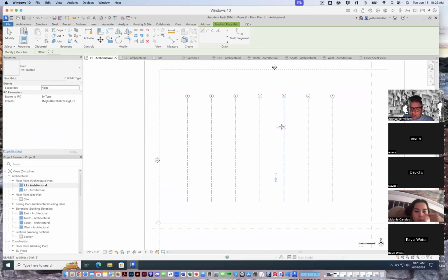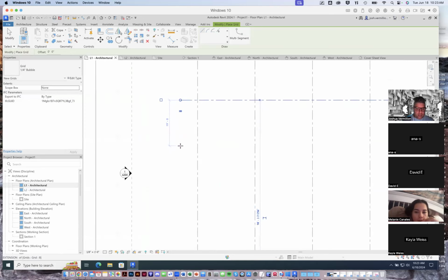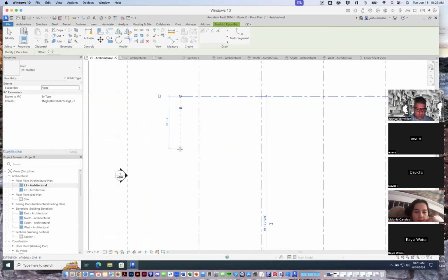And we said that our site is 44 feet wide along Las Vegas Boulevard. And so I'm just going to go ahead and establish a grid line for the sort of northern boundary of our site. 44 is divisible by 2, so I would go 22 feet. If it's only giving me like 4-foot increments, maybe I just zoom in a little more and I can get more granular increments. In fact, the more I zoom in, the more control I have over things. 22 feet.